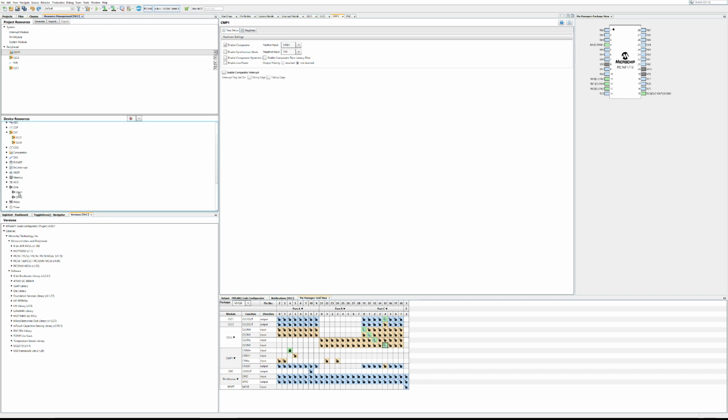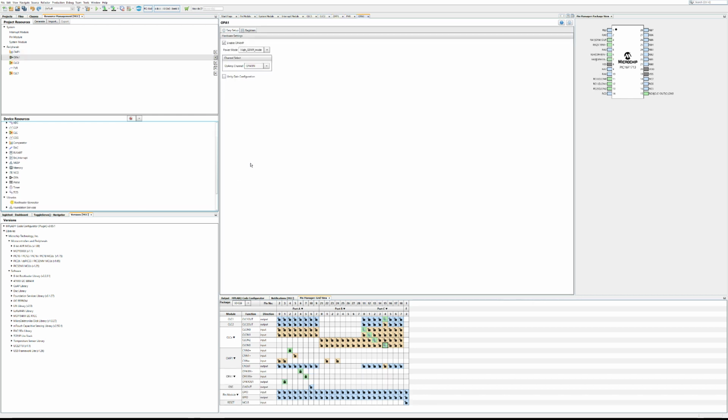There are also op amps. You have 2 fast, high bandwidth rail-to-rail op amps. They're very, very useful both to buffer the internal DACs, so you can get some decent current out of the internal DAC, but also to utilize as a generic op amp.